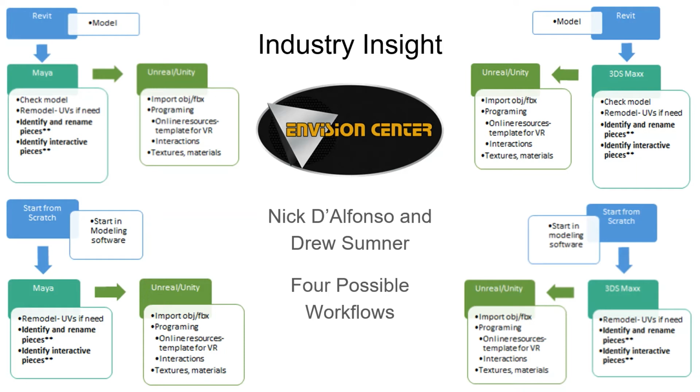Another option was to start from scratch in Maya or 3ds Max to avoid too many problems that sometimes occur when converting from Revit files to FBX. Within either 3ds Max or Maya, go through and check the model, remodel any objects that need it, and after the objects are perfect and the UVs are good enough to add textures, then the model can be imported into Unreal or Unity.